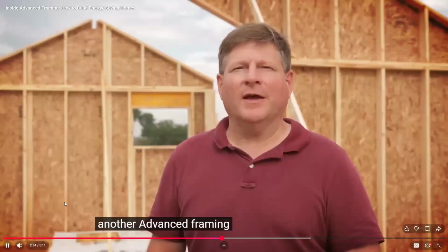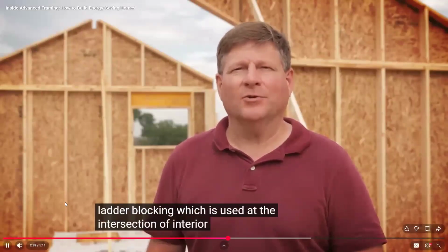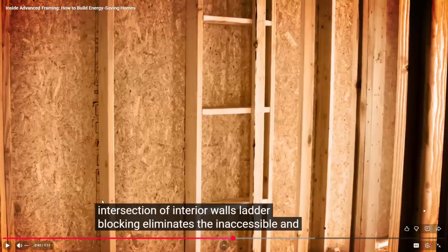Another advanced framing technique, ladder blocking, is used at the intersection of interior walls. Ladder blocking eliminates the inaccessible. He's going to show you two different kinds of ladder blocking. So this one, the ladder is set up so that the stud goes the full depth of the wall. He's going to show you another one where you turn that thing vertically, and then that gives you continuous insulation.